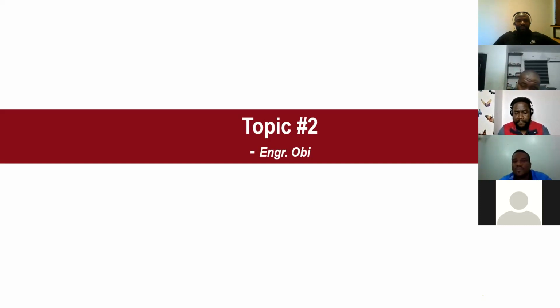So now your synchroscope, depending on if you have 4 generators, you have a switch for 1, 2 to 4. Now, number 1 is online, I'm bringing in number 2. I switch my synchroscope to number 2. That is, I want to bring number 2 to the switchboard. The moment you switch it on to number 2, your synchroscope starts dancing around. You have clockwise and anti-clockwise. If it is running clockwise and too fast, you have to decrease the speed of your incoming generator.